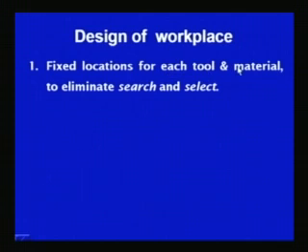The workplace should be designed keeping in mind certain aspects, like a fixed location for each tool and material should be provided, so that it will not require unnecessary searching and selection related steps, because a lot of time is consumed in finding the desired item and then getting it for carrying out the further operation, either assembling or further processing of the raw material or using the tools for further processing.